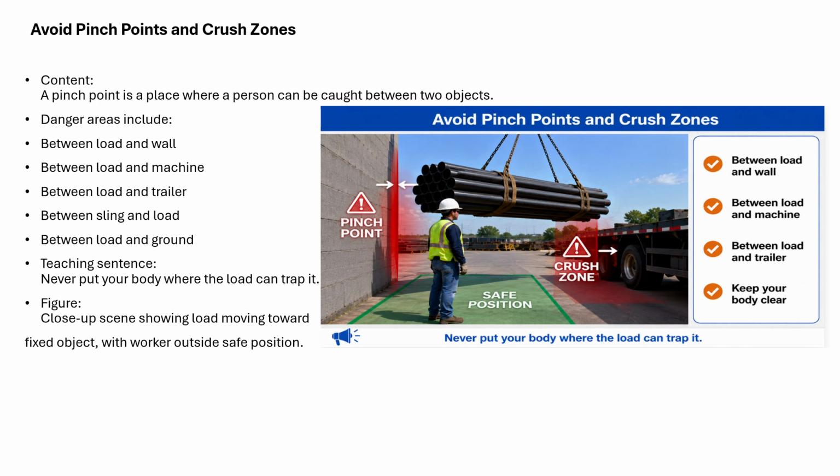Never put your body where the load can trap it. Close-up signs show the load moving toward objects, with workers outside in safe positions.